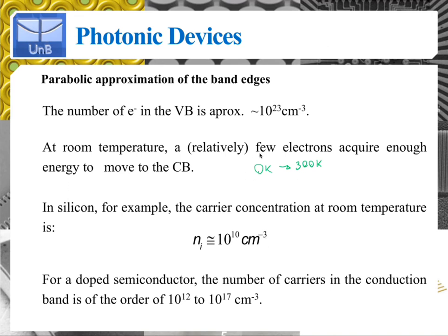As opposed to 0 electrons at 0 K, if you raise the temperature to 300 K, you now have a few electrons close to the edge of the conduction band, and because these electrons moved up in energy to the conduction band, they leave behind a few holes, which I'm going to draw like this, the empty circles in the valence band.